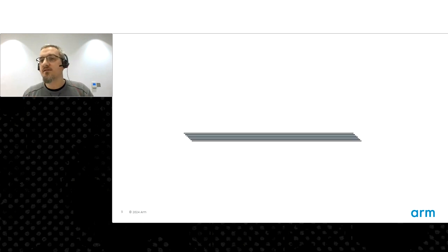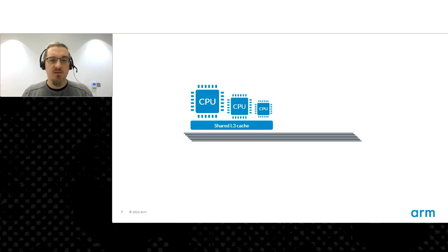What's inside one of these SoCs, at least in terms of the main compute subsystem? So we have a memory bus that links everything together, and you will have a variety of CPU cores. For modern ARM systems, there's normally 3 different types. And typically for an Android phone, you'll have 8 in total. The small cores give you the best energy efficiency.